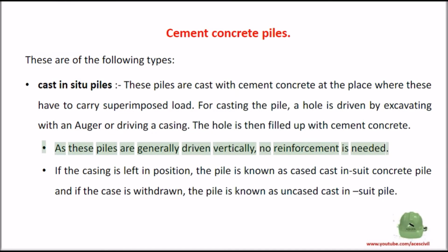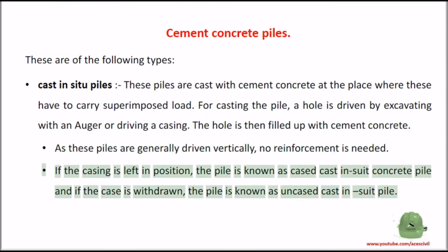As these piles are generally driven vertically, no reinforcement is needed. If the casing is left in position, the pile is known as cased cast in situ concrete pile, and if the casing is withdrawn, the pile is known as uncased cast in situ pile.